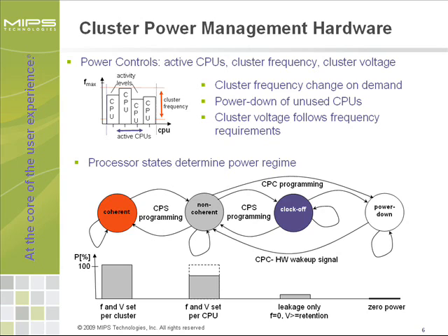Second, performance demands fluctuate temporarily. Given the communication requirements between CPUs operating in the common coherent address space, these CPUs should run at the same frequency and voltage level to ensure low snoop latencies. CPUs in non-L1 coherent operation, however, can assume independent performance levels through individual frequency and voltage change.